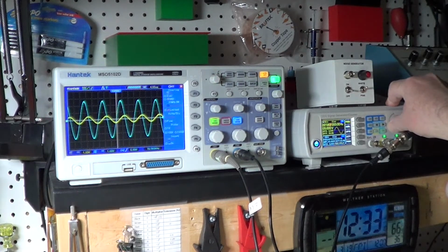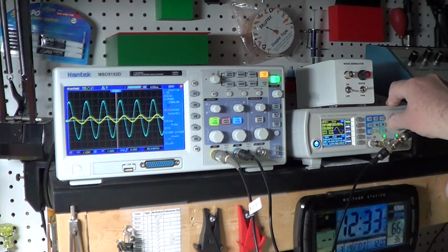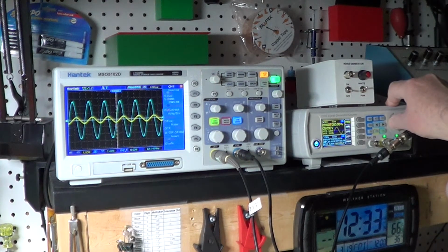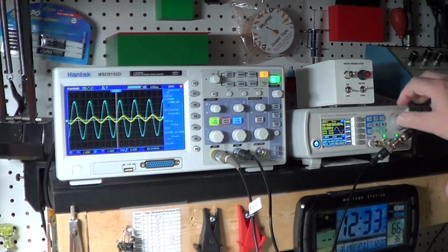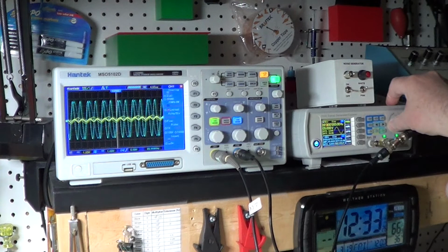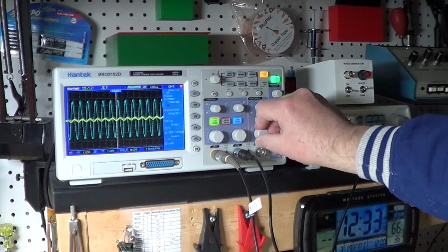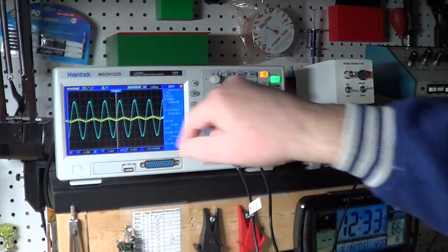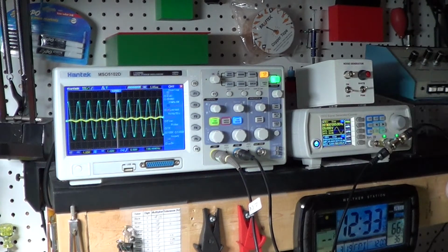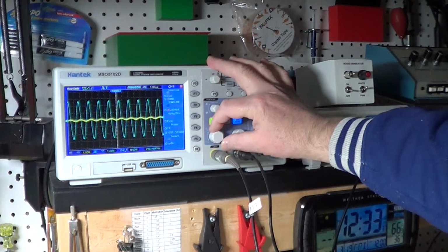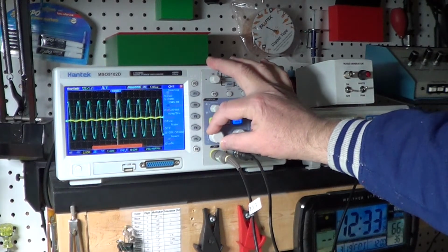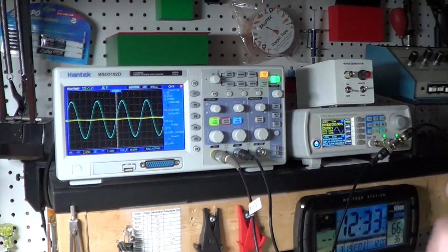You see now I keep increasing the frequency, but at this point there is no more change in the phase shift. However, the level of the signal keeps going down, down and down further. Let me show you what happens when I go really far up. For example, 200 kHz. See, the signal is almost gone. 300 kHz. Even lower, but the shifting has stopped, as you can see. And the signal is almost gone now.